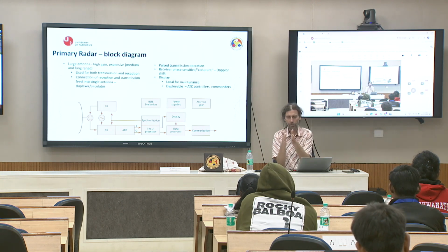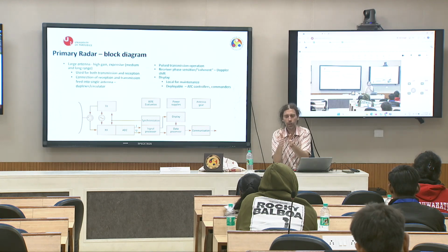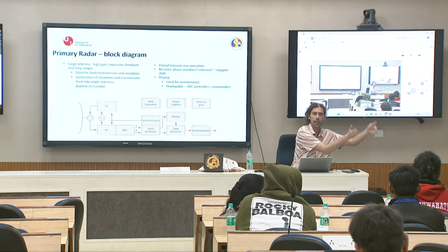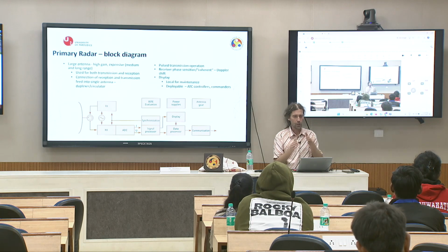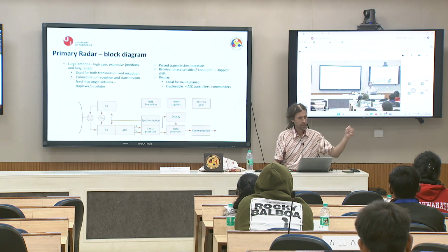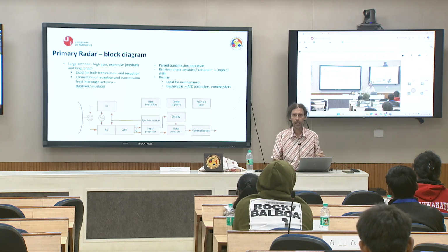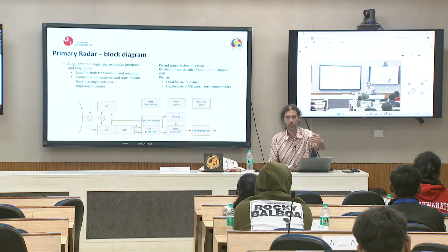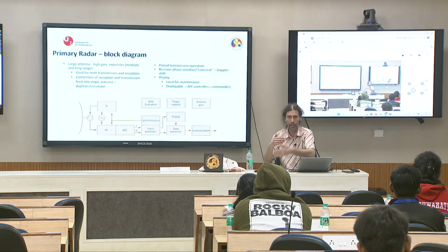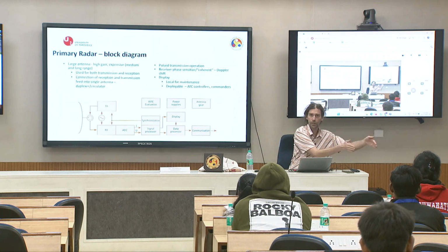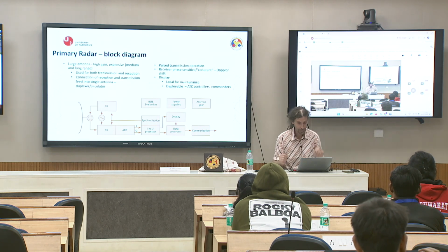So it is like you have in parallel 5-10 filters. And the first filter detects targets that have speed from, say, 10 km per hour to 20. Second filter from 20 to 40, from 40 to 60. You get my point. And the input to the bank of filters is your IQ data, and of course only through some filter will it pass, because other filters will attenuate it, because every filter is designed for a specific speed range. Like this example.